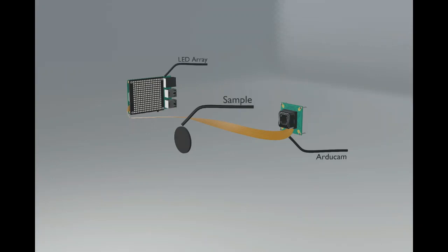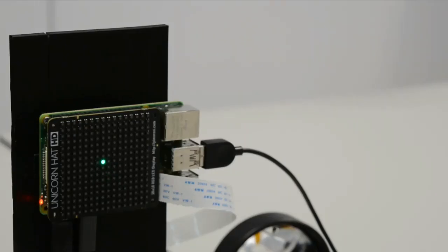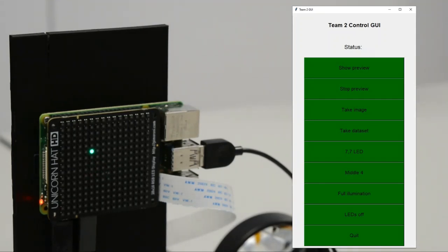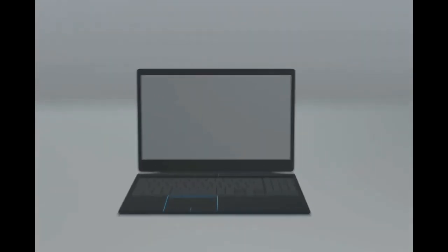Image acquisition tasks relate to the control of electronic components in the prototype system. This involves implementing a user interface which controls the illumination sequence and camera exposure. For the camera control, a variety of exposure modes were evaluated for this purpose, with the optimal for this project being identified as the night mode, which minimized saturation in the image.